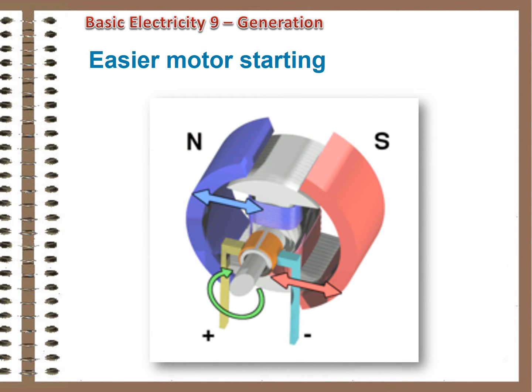By their nature, single-phase motors are difficult to start. The opposing magnetic fields that cause rotation just switch back and forth. It's a minor issue in small motors. Their tiny inertia is overcome with relatively simple wiring tricks. But large motors are another thing.